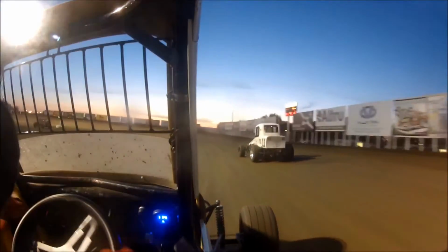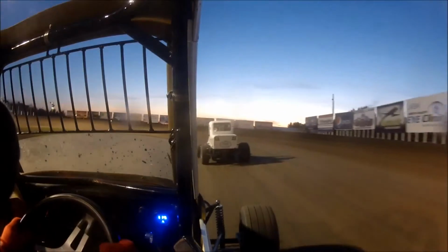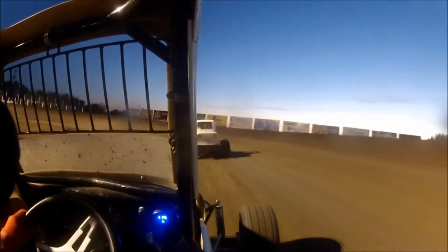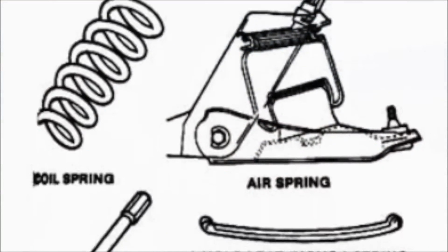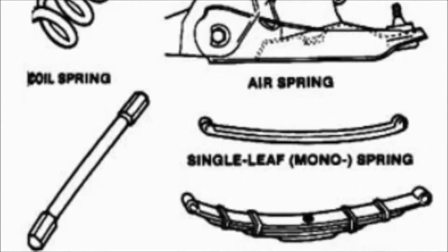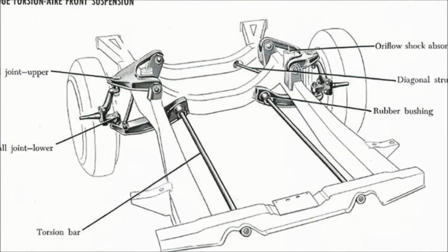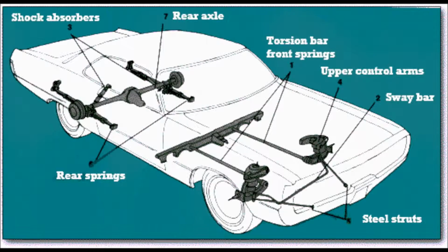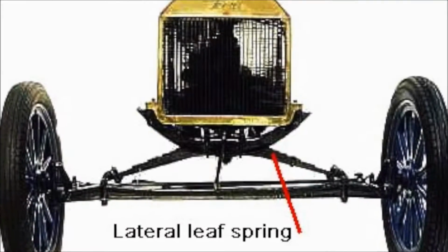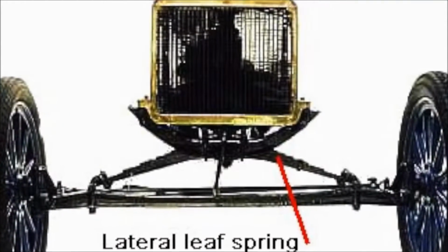Springs are a multi-purpose tool used in the suspension of a vehicle, allowing for precise handling, ride comfort, and load bearing. Springs are used in relation with shocks as part of the suspension of a car. Here, a torsion bar is shown. It is generally preloaded by either a clockwise or counterclockwise twist. Torsion bars are not interchangeable, so they can only fit into the vehicle for which they were designed, a large disadvantage. Leaf springs date back to the very first automobiles.